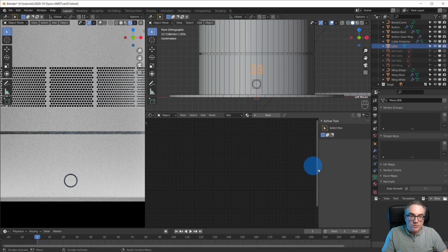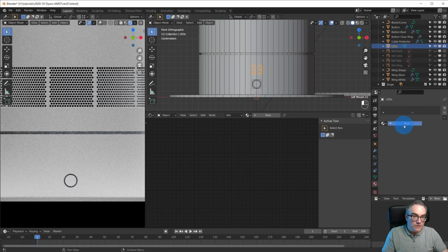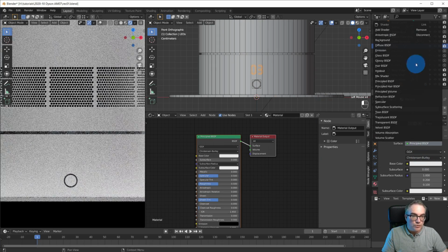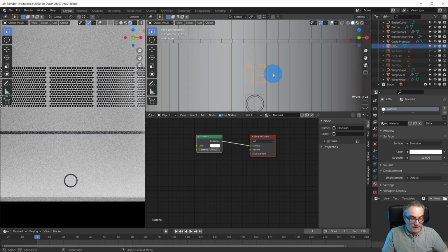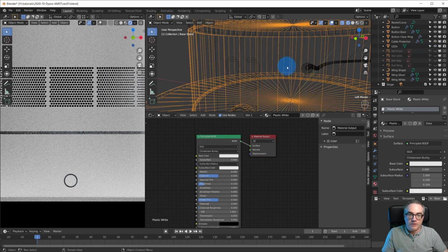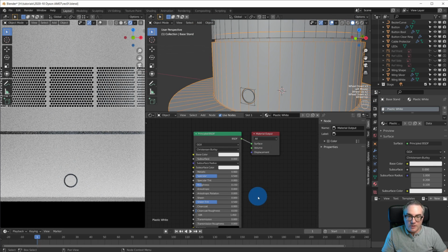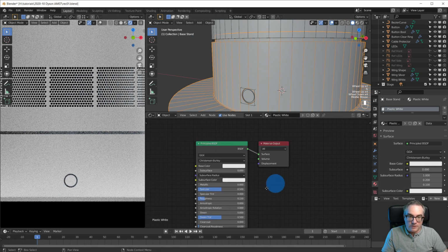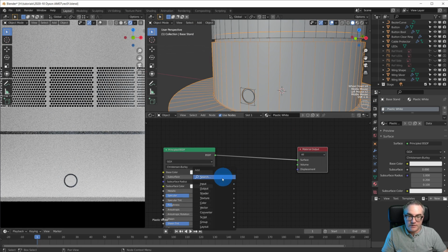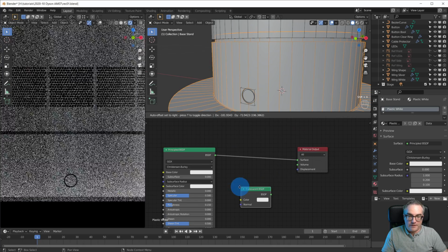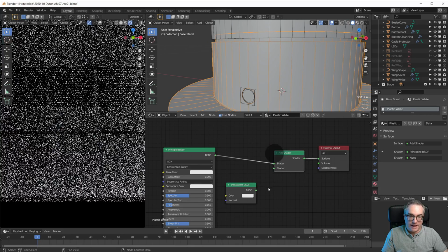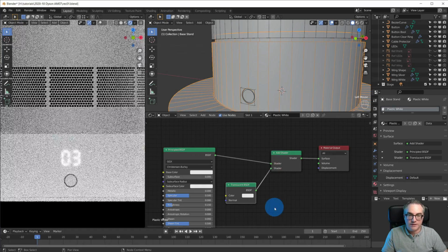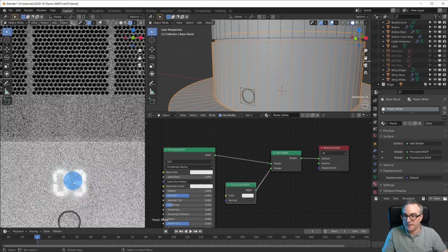But first of all, let's go to the LEDs. Create a material over here. Set that to emission, white, and I don't know, strength 10. We still can't see it because it's inside. So we have an emission on here, and now on this guy, we're gonna change the material here. We're going to add a shader, translucent, and we have to shader add that to our plastic. And look at that, it shines through.